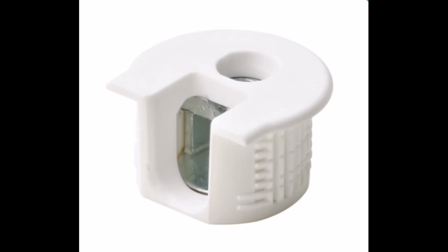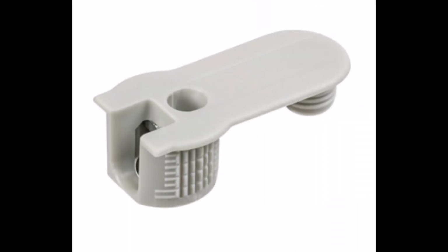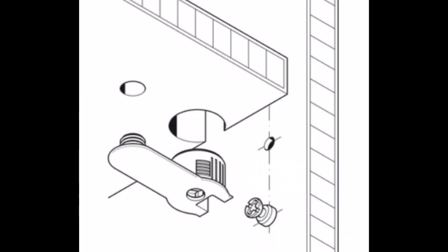They provide some of the same practical advantages as a cabinet connection, but use a cam-style connector, different machining profiles, and some hardware trade-offs. The cam outrigger is a variation of this type of connection that includes an additional pocket behind the main connector to house an additional dowel for extra stability. The cam joint also provides more control over the machining dimensions, so one could use it to create other Rafix-like connectors, such as those made by Hettich. Let's see how this works.